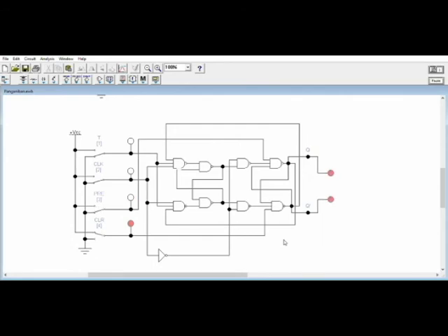Next, we are going to toggle the output. The T flip-flop will be initialized. Let's turn on the toggle, make a clock pulse signal, and turn off the preset. And now, as you can see, we have toggled our output. Our T flip-flop is initialized.